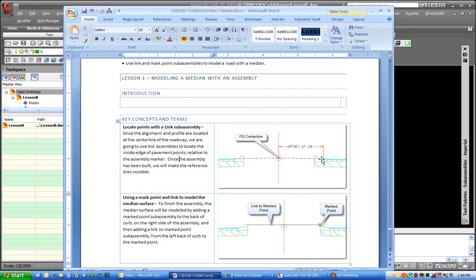The second piece to this, to finish it off, is that we need a link across the top going from back of curb to back of curb, and I need that to be variable. So as I transition my pavement sections, or if we alternate the grade or elevation of our edge of pavements on the two sides of the road, I want a link that connects from back of curb here across, so we get a nice straight grade across there. And we do that with two sub-assemblies.